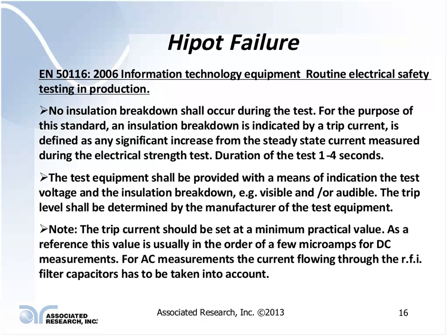Why would I want to set it for 100 milliamps? Well, the standard may allow me to, but you could have some issues come up where you could have a high resistance fault within your product that you may never detect if your current trip threshold is set that high. I've seen it.